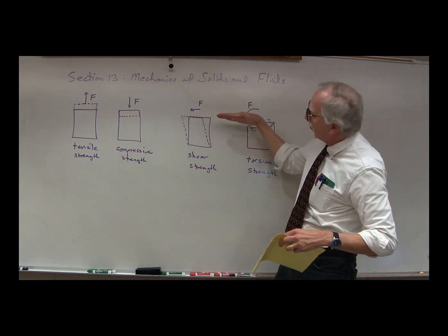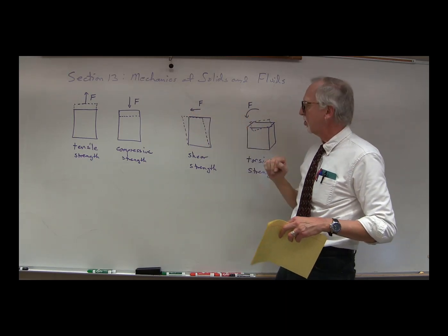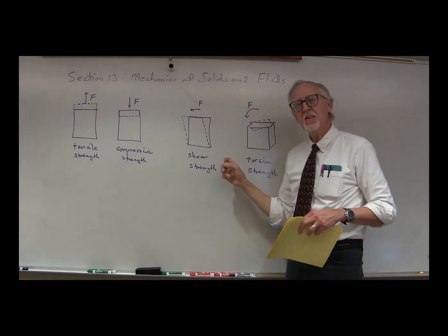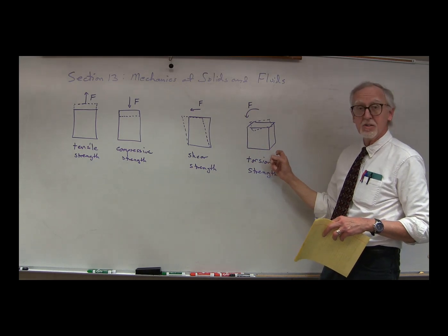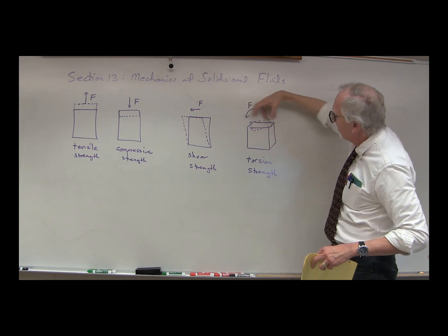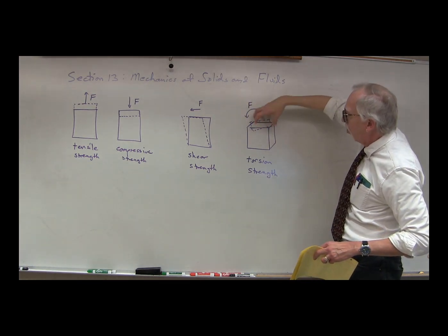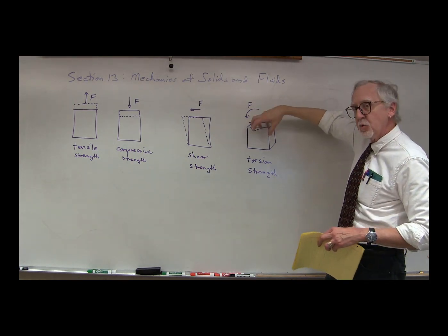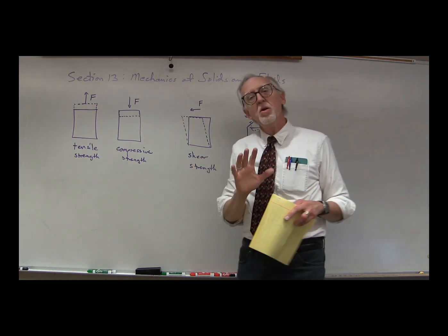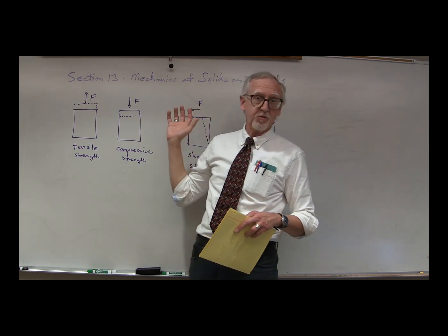Also, what if you push something to the side so that it deforms by kind of bending at an angle, so to speak? That's a measure of its shear strength. And the shear strength is also very similar, the same for many materials, to the torsion strength. So rather than just moving the top surface to the side, say, imagine you try to apply a torque and try to rotate it. How much will the material rotate? That's a measure of its torsion strength. So basically, these are all how solids respond to these various types of forces in different directions.